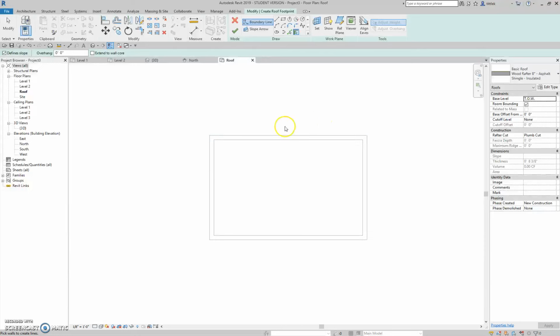Again, you can easily connect lots of things in Revit to each other, so that if I move one thing, a lot of other things move with it. That's sort of the beauty of Revit. Everything's interconnected. When I change this from the line tool to the pick wall tool, you'll notice that my drawing options change. We are going to leave this set at define slope.